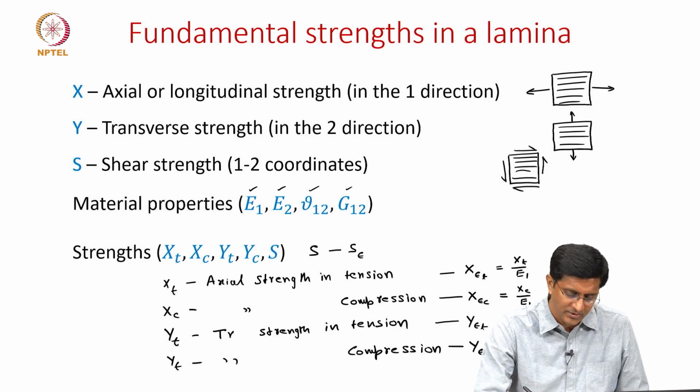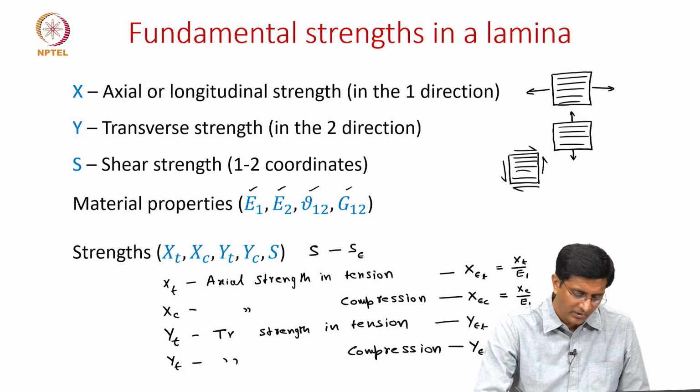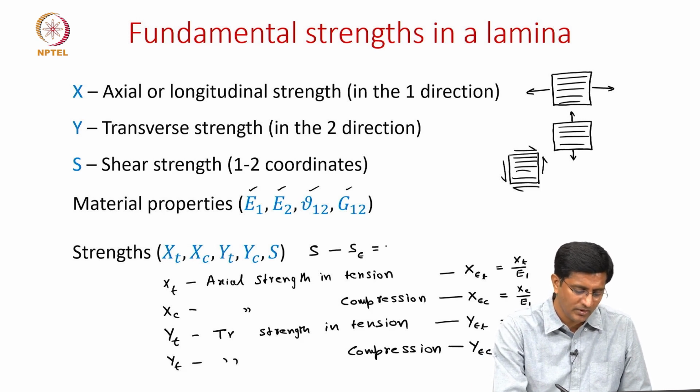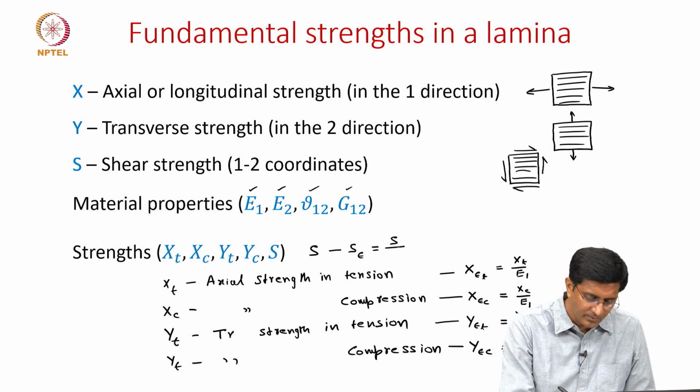For the transverse strains, we'll write it in terms of YT by E2 and YC by E2. And lastly, for the shear strain, the failure shear strain, we'll write it in terms of S by G12.